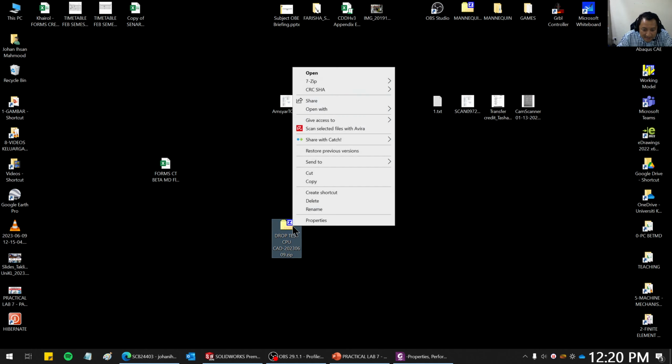I can hide it. So again, let's go to simulation, new study. And then let's go to drop test and then click OK.